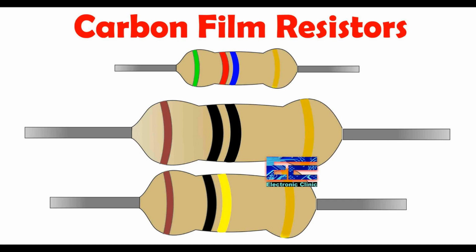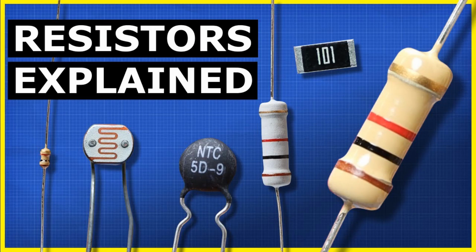Noise stability. In addition to resistance value, stable resistors should have low noise characteristics, meaning they do not introduce significant electrical noise into the circuit. This is crucial in precision measurement and low noise applications. Aging stability. Some resistors may experience changes in their resistance values due to aging effects. Stable resistors are designed to minimize these aging effects and maintain their electrical characteristics over time.